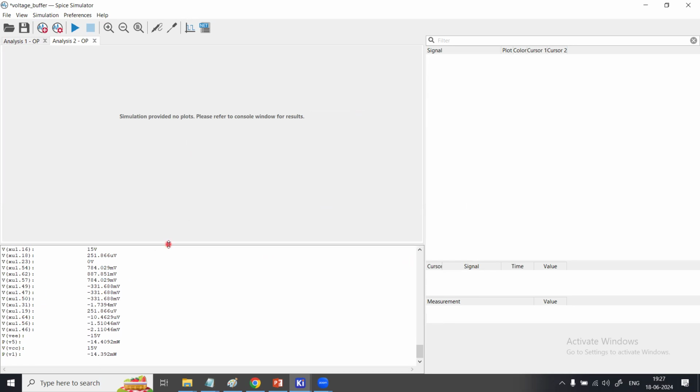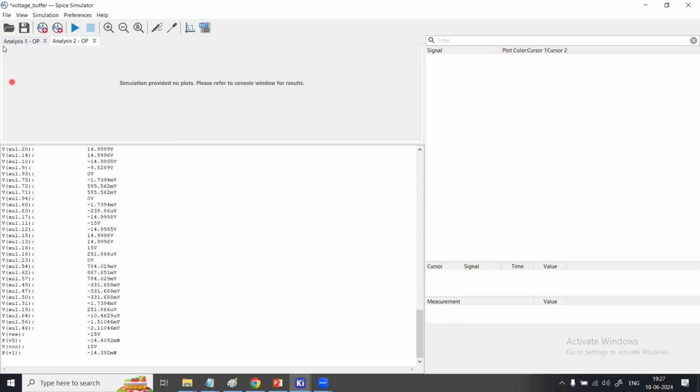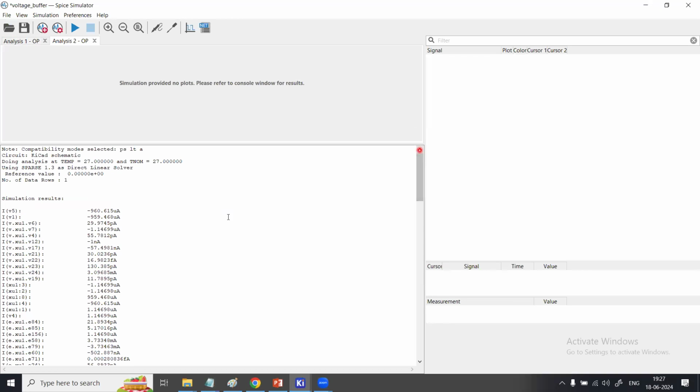So now look at this. I got a whole range of values and parameters to understand. X stands for the components inside the sub-circuit. I stands for the current from the voltage source. V5 is about 1 milliamp, close to 1 milliamp. V1 is 1 milliamp, and then this X stands for inside the sub-circuit. Ignore that. Here 1 microampere from the input signal source, because we have used the 100 millivolt. I will scroll it down.